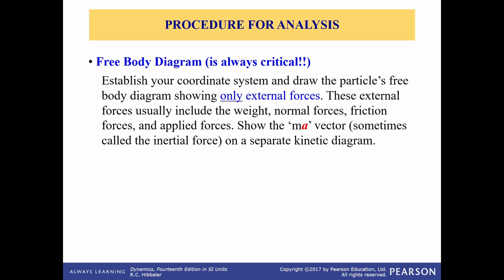You need to draw the free body diagram. First of all, establish your coordinate system. What is the coordinate system in this case, meaning which plane you are going to use for indicating the x and y directions, and draw the particle's free body diagram showing only external forces.